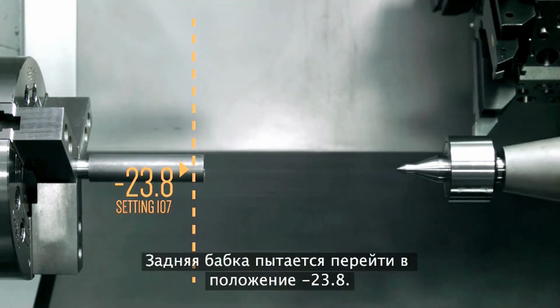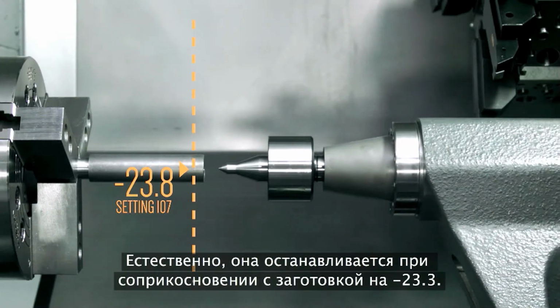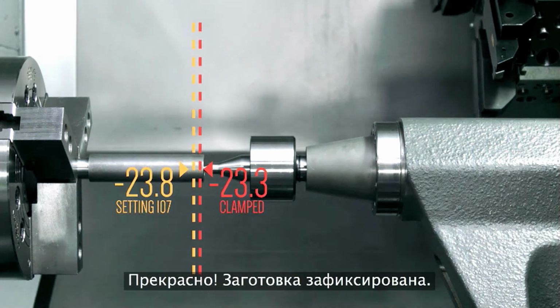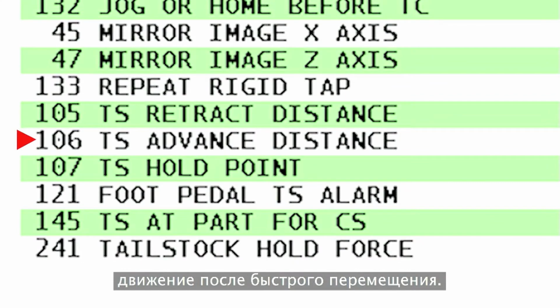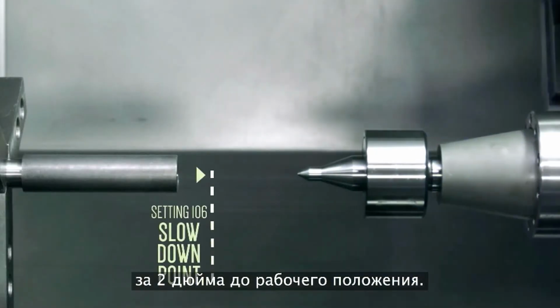The tailstock is trying to reach negative 23.8, but of course it stops when it hits the workpiece at negative 23.3. Great, the part is clamped. How about setting 106? This setting tells the tailstock when to slow down from rapid motion. We'll leave it set at its present setting of 2, which slows motion 2 inches before the hold point.